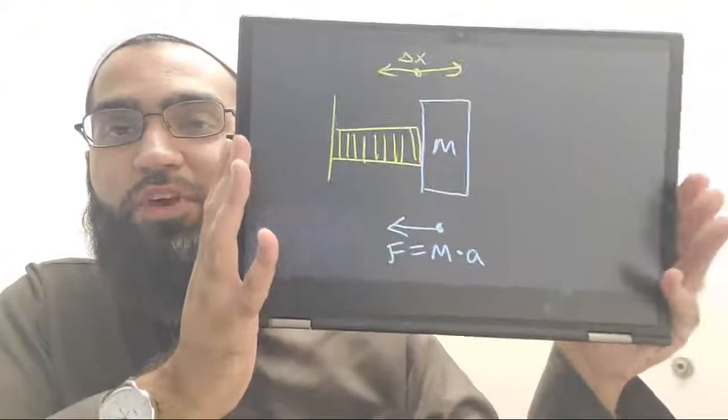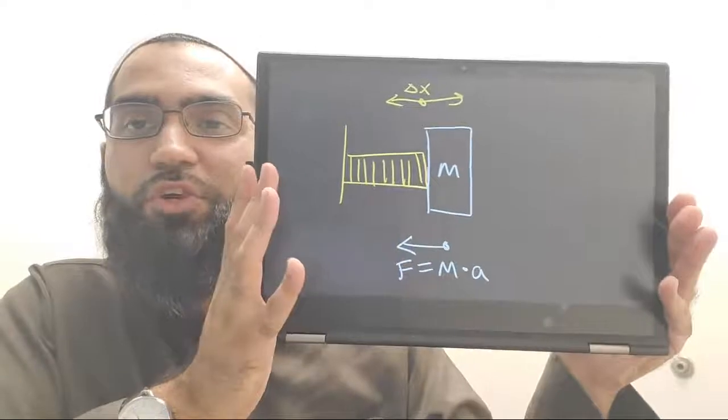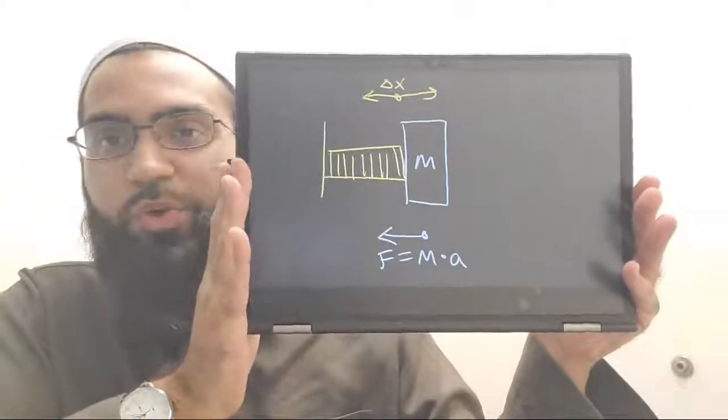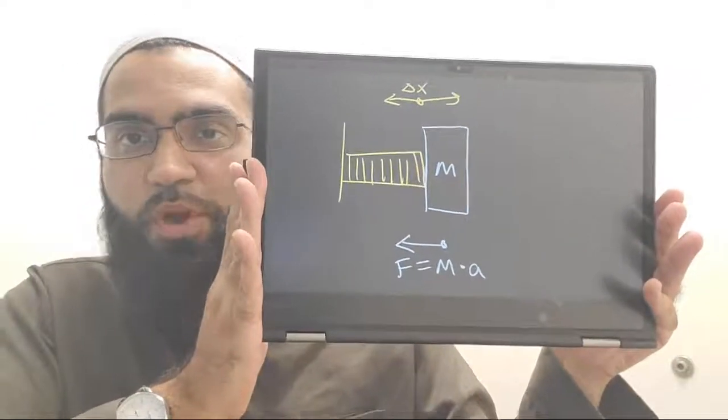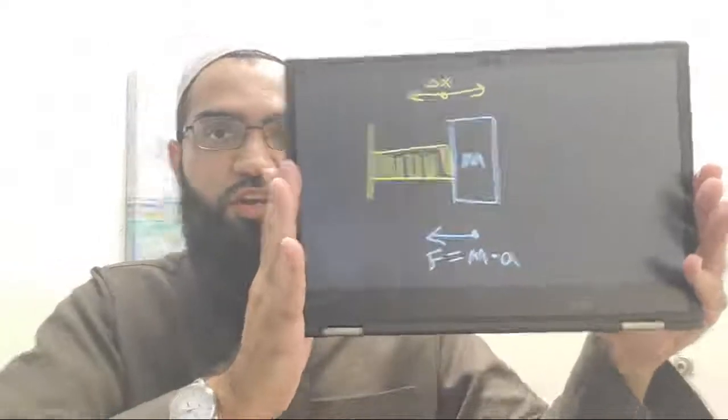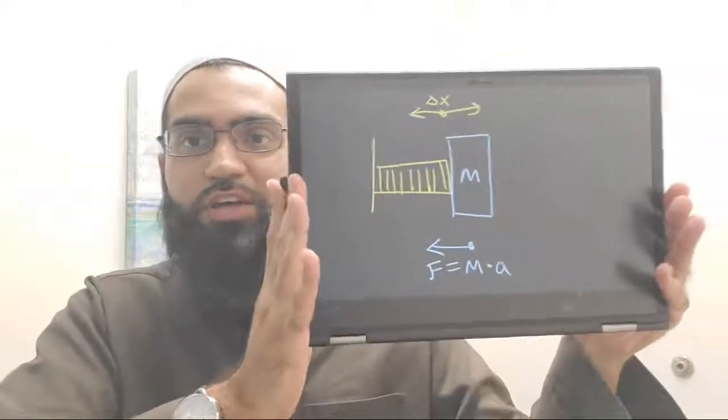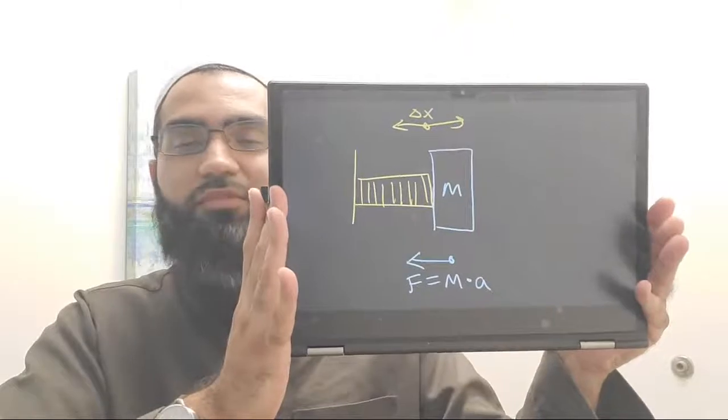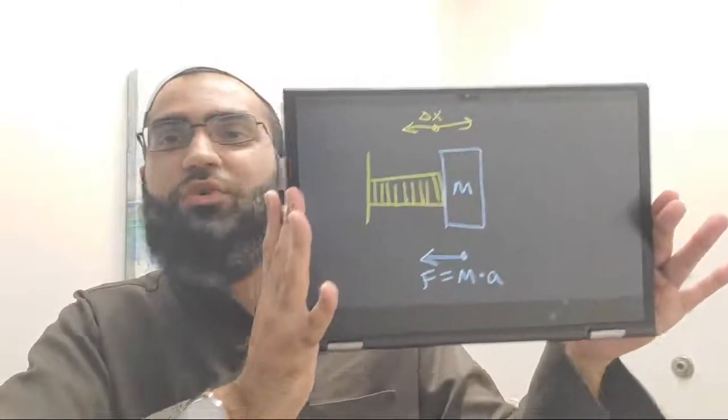All right, let's take a look at how we can figure this thing out, how we can determine all these terms, so you can come up with a nice actuator equation, so you can measure current in your application, and you can get out your velocity and say, look, boss, we don't need to have these external sensors. We got our piezo can do it all for us.